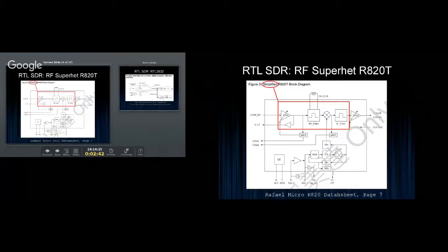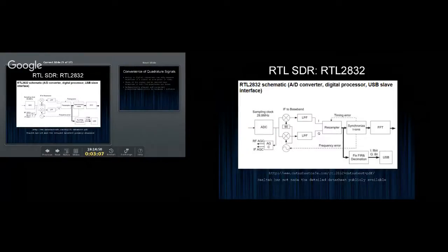The last talk that I gave talked about the RF down conversion front end, so this is just continuing on from that idea. This is the RTL SDR chip that does the down conversion, and what you see on this side is the intermediate frequency signal out. Now that's one signal. You still need to be able to convert that to in-phase and quadrature components. I did scratch my head a little bit about this, because this is the digitization end, and they are using a single analog to digital converter. So perhaps they are deriving the quadrature components in the digital domain anyway.